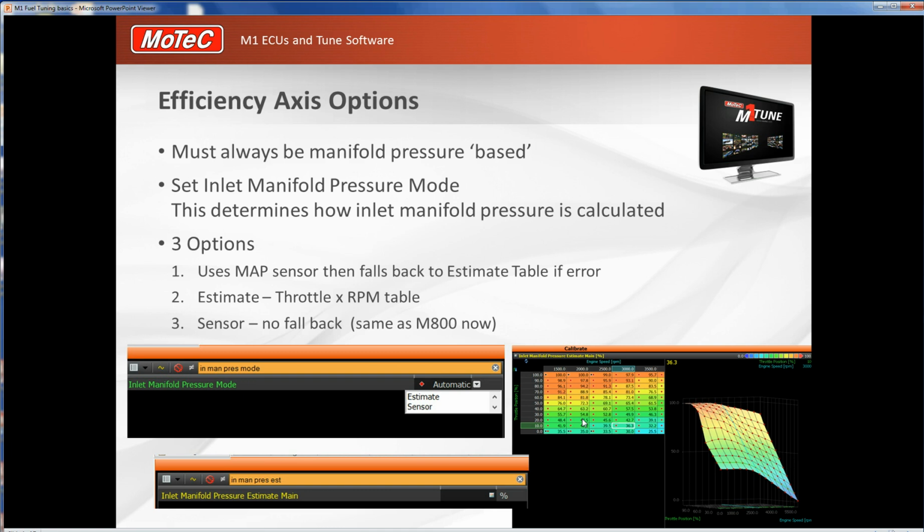Later, when we tune the efficiency map, the engine will be able to make a reasonably close assumption of what the airflow through the engine is at the time. Even if it miscalculates that, the result will still be the same. You'll be able to tune the efficiency map to make the engine richer or leaner. It just affects some things downstream that we can talk about later.